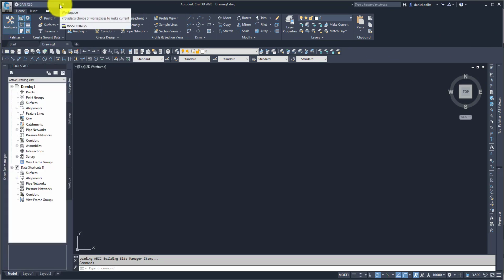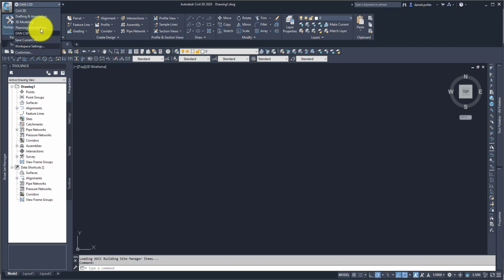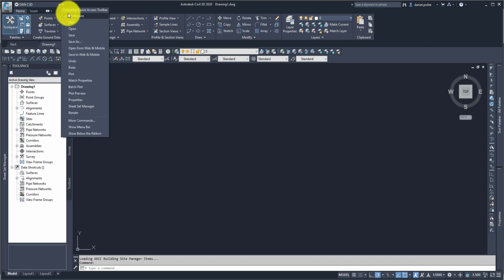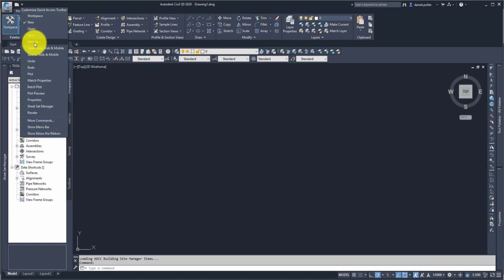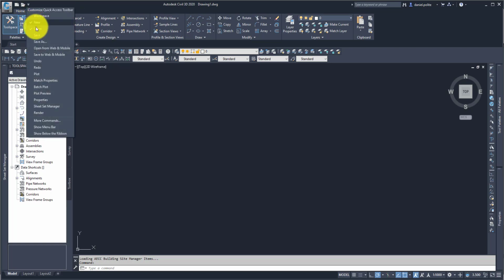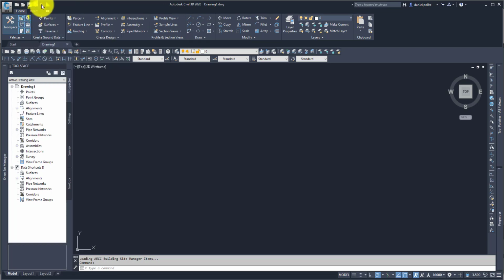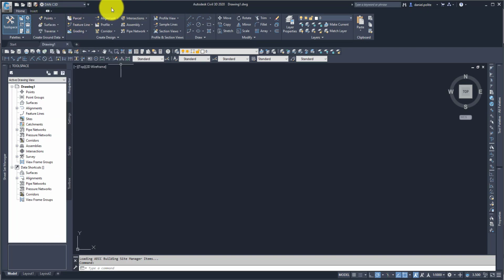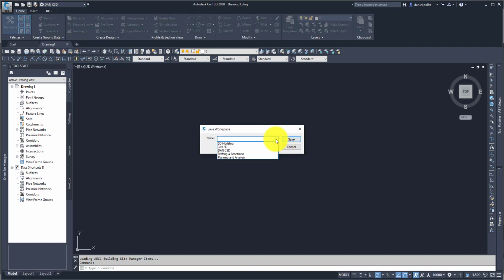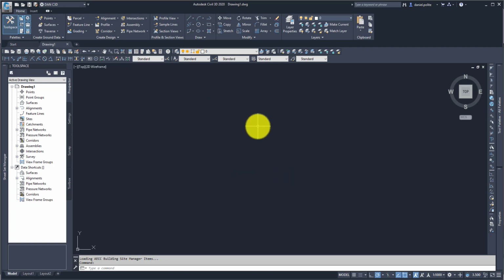You'll notice that the customized toolbar didn't come in, but you could put in what you want on that with the little down arrow, and as you add these, it'll go in the order of how you want it. And then now that's my workspace. So now I can hit my save current workspace as, and I can select my Dan C3D, hit save. Yes, I want to replace it. So now I've updated again, and my workspace is set.